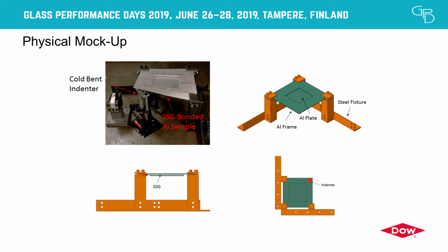And so that allowed us to, and then we had these points of attachment. We're pinning the sample here on three sides, and then we have just a simple hand jack, hydraulically actuated, that can deform or bend the plate here, and then hold it in place so that we can look at what's happening with the spring-like action of the deformed plate onto the sealant, replicating what we would see in a cold bend application.